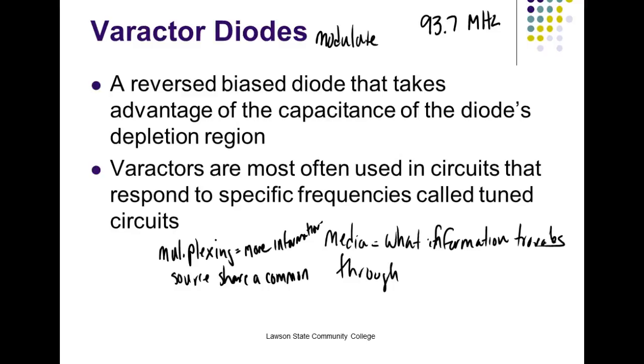So what you're doing is you tune your radio, you're setting up a tuned circuit that allows the carrier for a certain frequency to come through, and then what? Then we strip it off with filters. We strip off the carrier, and then we let the information come.